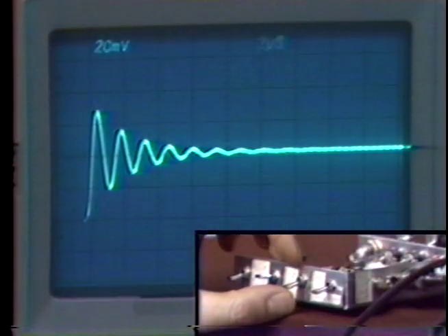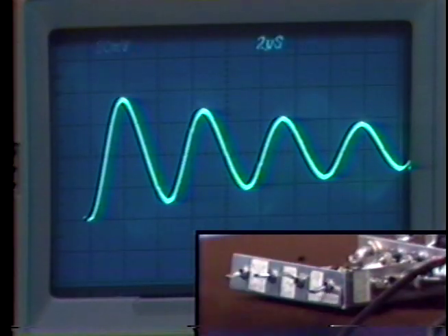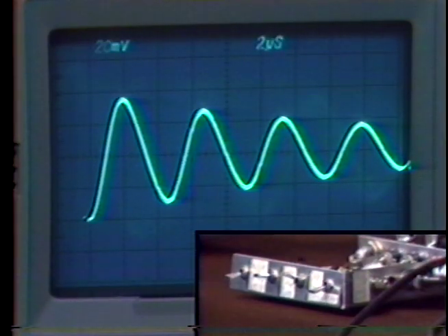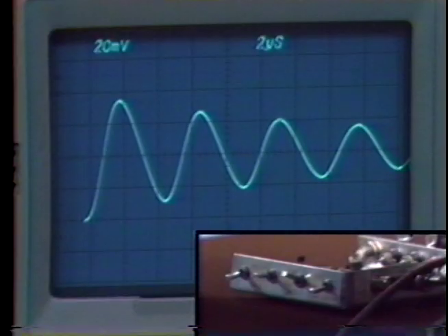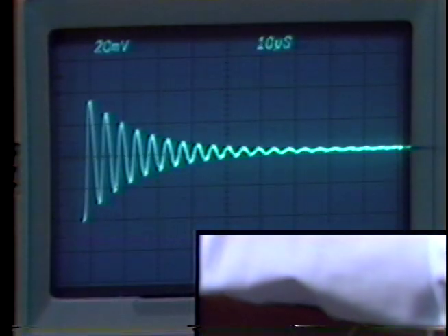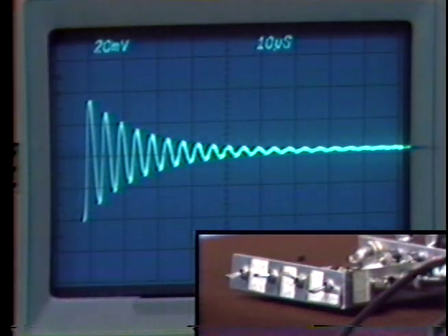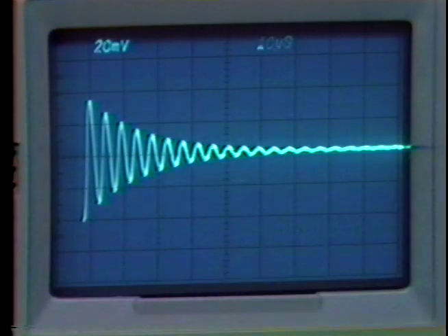Let me load the amplifier with a 1/10 of a microfarad capacitor. When we do that, we'll have to slow down the signal generator just a bit. Here again, we notice a further deterioration of relative stability, considerable overshoot. We're now at 10 microseconds per division, and we notice that the response still is wiggling 100 microseconds later.